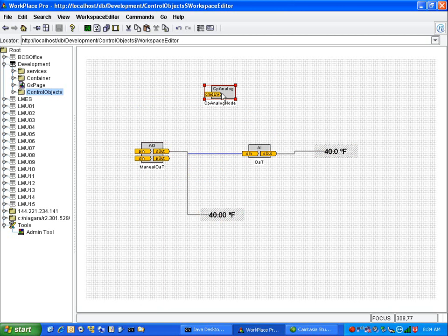For those of us with LAN experience, analog command is the only object that can read and write to an NCI type snippet. We got familiar with them awfully early because when we started Niagara, we were heavily into LAN controllers. NCIs were pretty popular, and the analog command object was the only one that could link to an NCI. The other thing we can do with the NCI value is actually use it to adjust certain parameters inside of other Niagara objects.